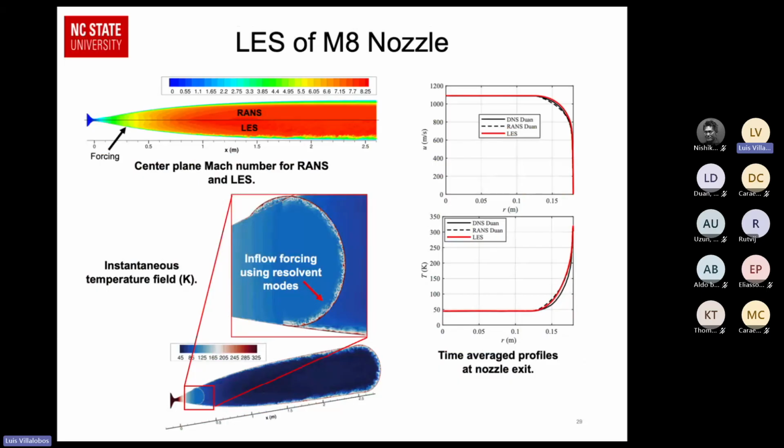Because you feel that's where we have the data, the skin friction portion doesn't match. Eventually it matches, right? So the recycle rescaling kind of matches from the other ones. I do have contours of the skin friction or U-tau for the nozzle. I did not include them. I forgot to, but I'll need to check that again to see where exactly we're getting the skin friction recovery. Yeah. Again, some people fix the mean flow with just recycle.